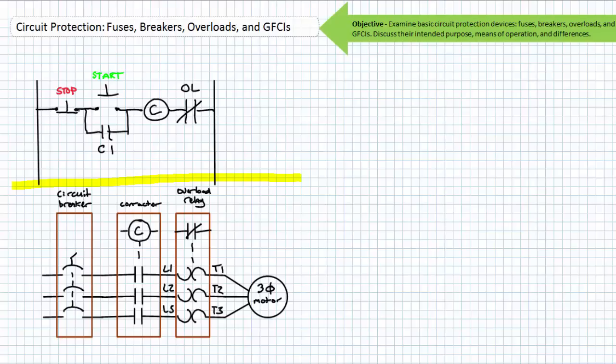A second method thermal overloads employ uses a metal alloy that passes directly from the solid state to the liquid state at a certain temperature, without a malleable, lumpy intermediary. This is called a eutectic mixture. The solid state of this mixture retains the spring-loaded switch, but the liquid state lets the spring-loaded switch move, and this switch is what, again, signals the control system to open the contactor.